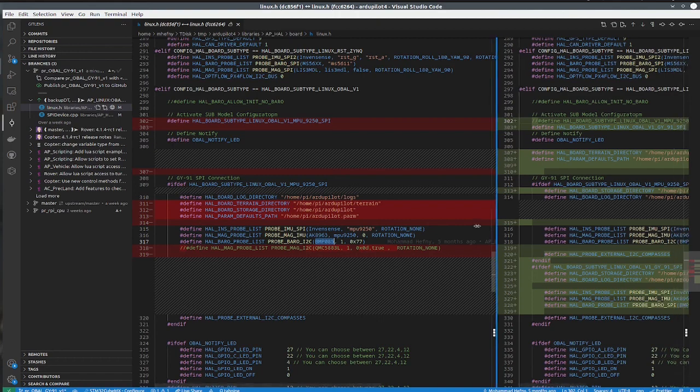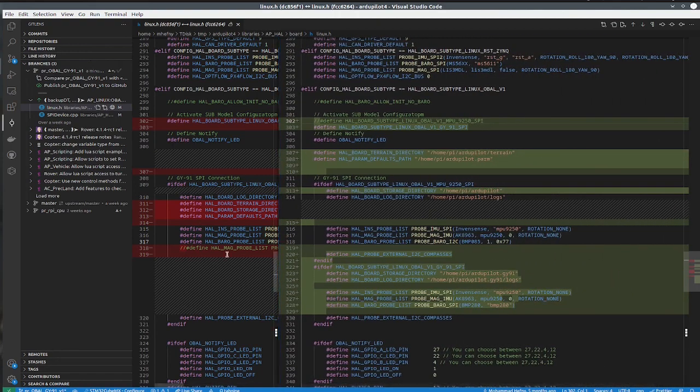Okay, the modification here: I split the definition of the folders. I added an extension here because I want to run the same Raspberry Pi on different shields. So when I put on the shield that contains the GY91, I run the Ardupilot applications, Arducopter or Arduplane, compiled using this definition, and then it will access this folder.